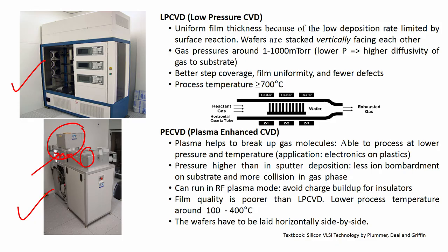It will load onto the substrate, and then there is generation of plasma. The chemical reactions will deposit the material on the substrate, alright. So, how does the process happen in this system? You can also see there is a vacuum pump. Here also we require a vacuum, but of a low order, alright, not like in case of PVD, where we require very high vacuum. Here it is a low order vacuum.